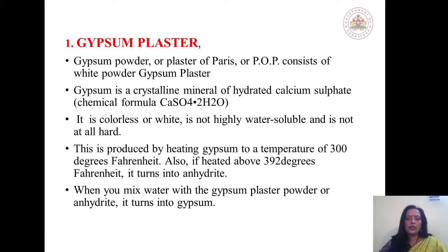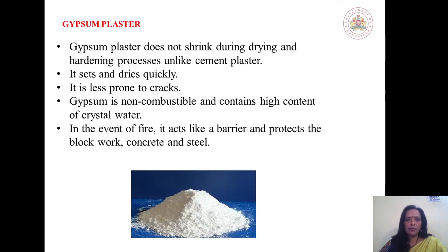When you mix water with the gypsum plaster powder or anhydrite, it turns into gypsum. The gypsum plaster does not shrink during the drying and hardening process, unlike cement plaster. It sets quickly and dries quickly. It is less prone to cracks.